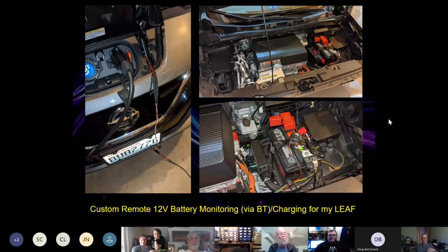I'm going to show you one thing that I did run into with my car, and we haven't broached this subject yet, but all electric cars have a 12-volt lead acid battery in them. That battery is the same kind of battery you'll find in any standard car. What it does is bring everything else up, but it also powers things that need to be powered when the car is switched off. So your cellular modem in there to allow you to get remote battery status and other things, all of the alarm system and all the standard 12-volt stuff.